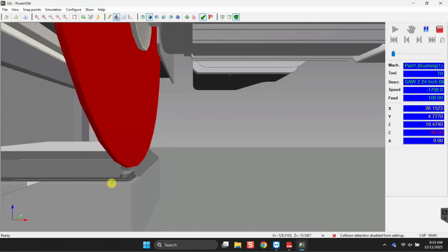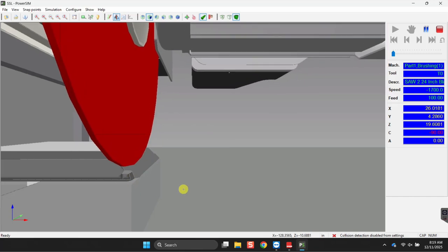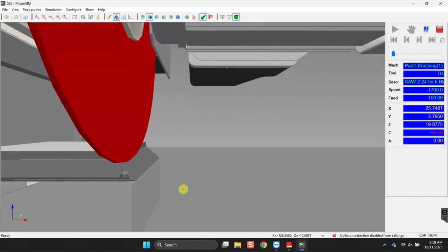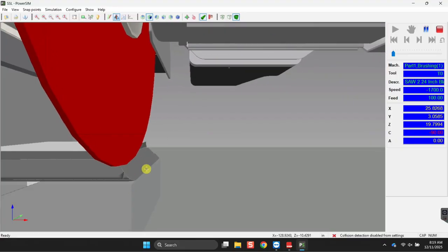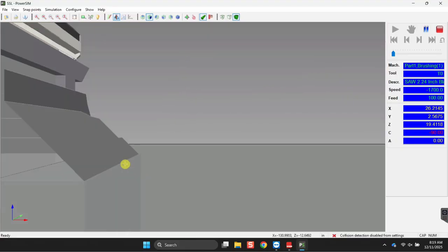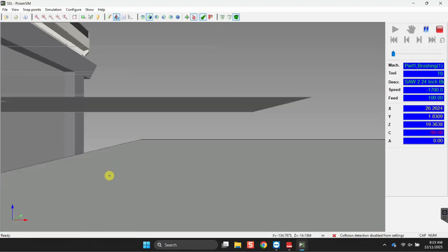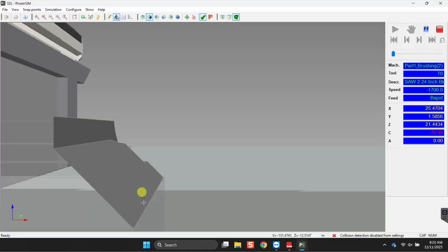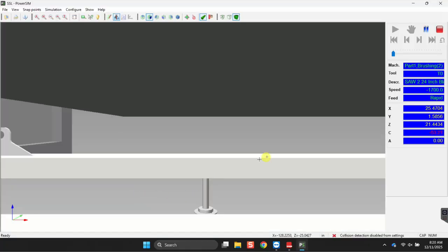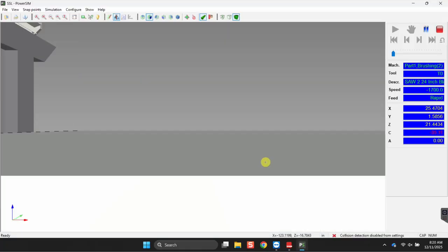That's it. She's getting full edge cleanup. There she is. So if we wanted more edge cleanup, I can't really tell in here if it's leaving a lip or not, but if it was, we would just extend your surface out using enlarged surface probably more.